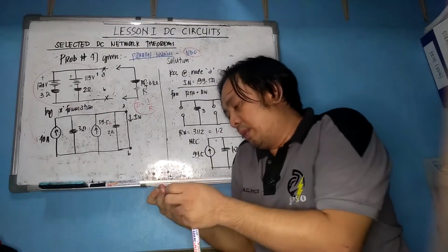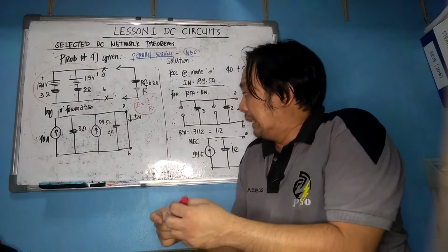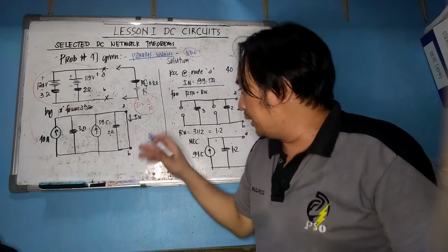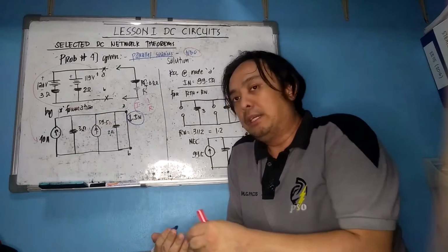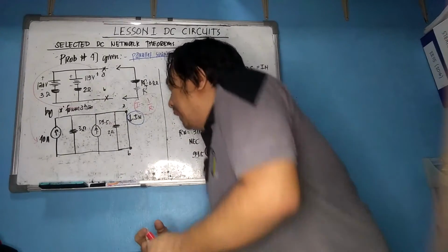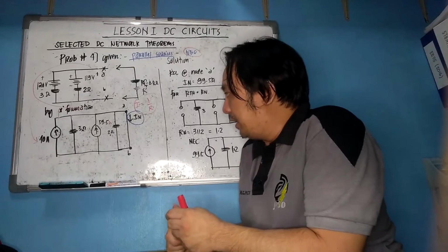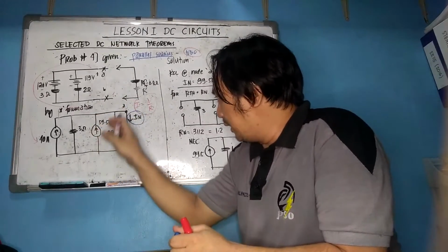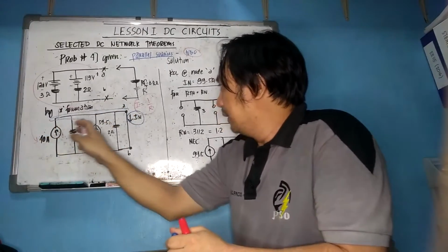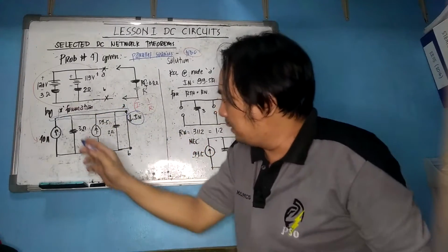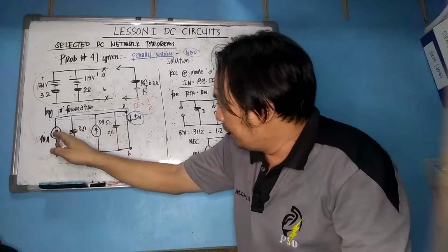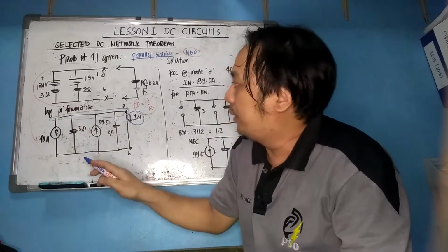And then, as we have mentioned in the basic fundamentals, to get the Norton current, you need to short the terminals and get that current there, IN. Now, to solve for that current IN, we have two nodes here, A and B. We have KCL at point A. By the way, I forgot to mention, how did we arrive at this direction here, an upward direction?